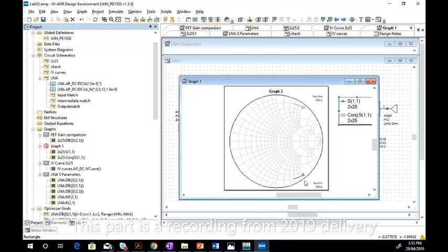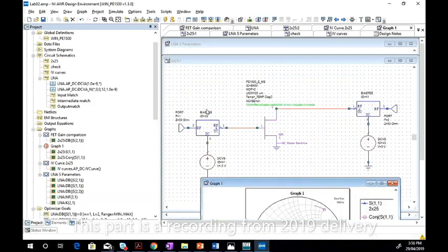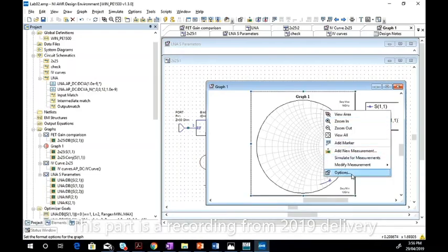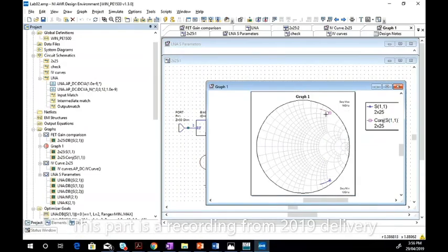So this is the impedance at the input of the gate. If you present an impedance like that, the imaginary parts will cancel out and you will end up with 50 ohm. That means whatever matching circuit you make has to go from 50 to around here. Let's say we pick the center frequency 14. We need to go from 50, which is 1, which is here, to here, right?